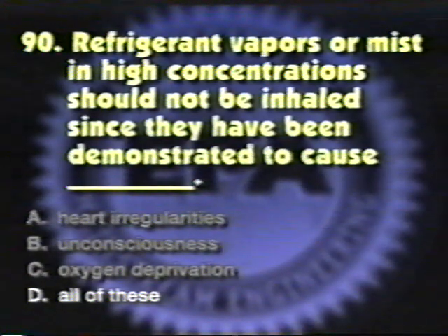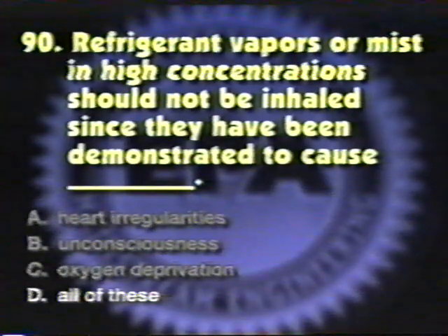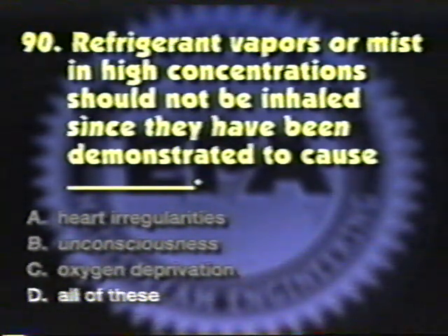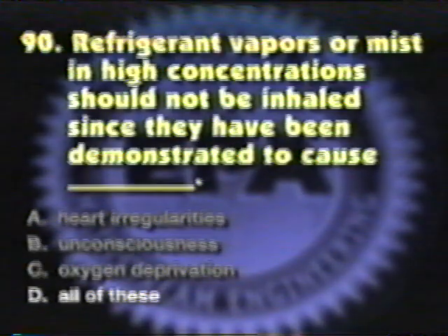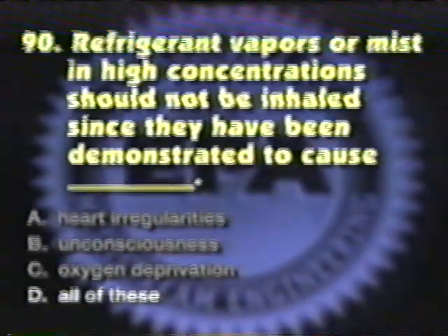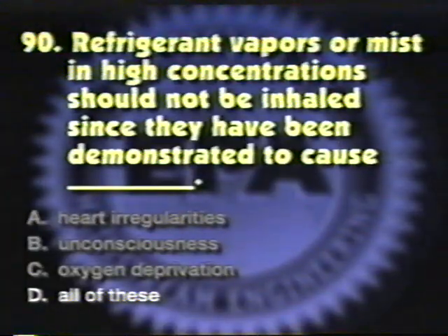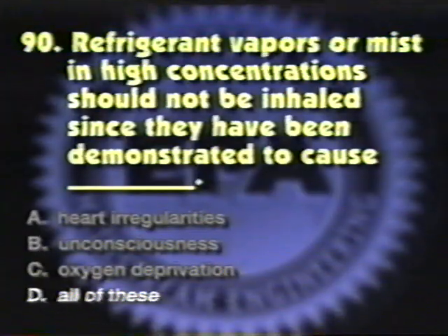Refrigerants are also heavier than air and can displace the air in a room, leaving no breathing air in the room, leading to asphyxia. In most refrigerant accidents where death occurs, the major cause is oxygen deprivation.